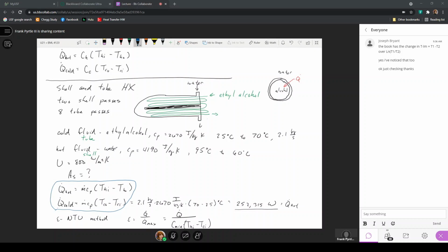So when you see a heat exchanger, whether it be online or you're looking through a catalog, and there's a range of values for the overall heat transfer coefficient, the company that designed that heat exchanger either directly did the calculations, or they sent it out to a third party that specializes in just measuring overall heat transfer coefficients for different heat exchangers, where they're measuring things that are directly measurable, mass flow rates and temperature changes, and using either a log mean temperature difference method or an effectiveness NTU method